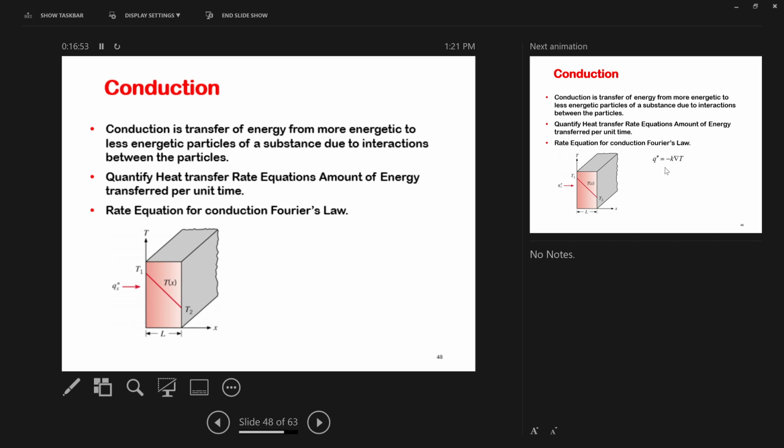So is that just Q equals negative K times area of PTDF? That's it. Or in more general terms, in three dimensions, you can just say that your heat flux, which is heat rate, total energy per unit area, is equal to negative K, the gradient of temperature, in each direction. So that's going to be your Fourier's law. And we are going to focus on the Fourier's law in the next lecture, because that will be the topic of the second heat transfer experiment we are going to have.